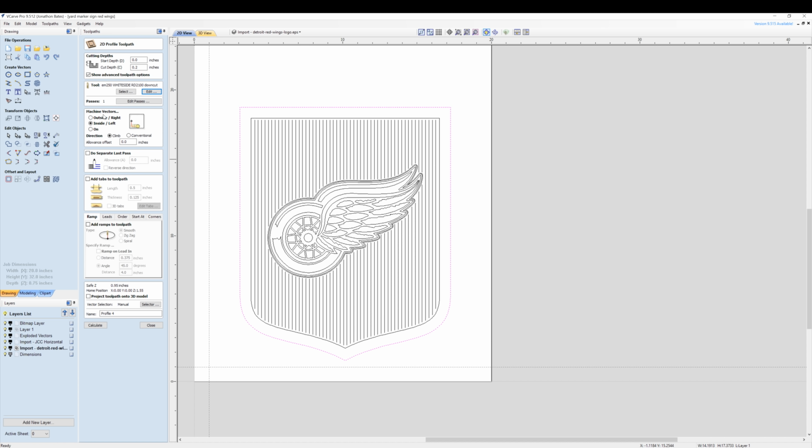We are going to make this on the outside. I've made this mistake of not checking this properly. We're going to cut on the outside, and I want to add tabs to the toolpath. Those tabs look okay. I'll leave them. Maybe a little bit excessive, but it doesn't matter because I'll chop them real quick with the chisel and flush trim them. No big deal at all.